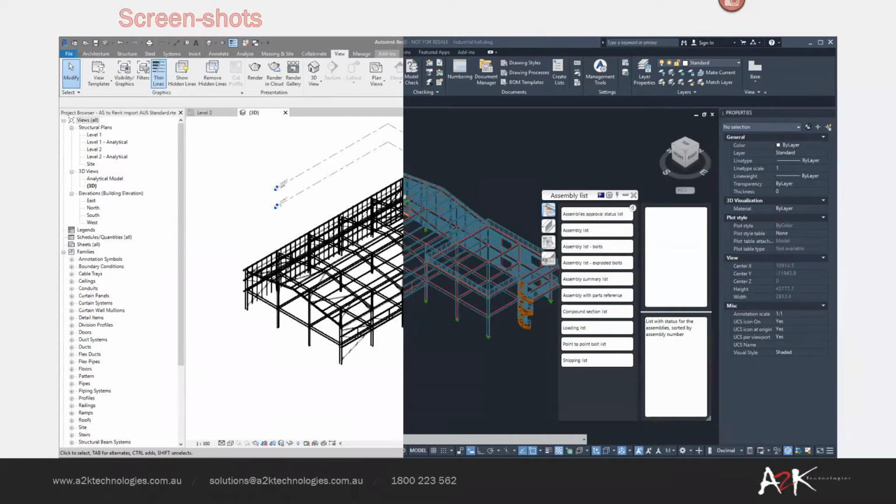The reason you would then push that through to Advanced Steel is that Advanced Steel has the ability to get out fabrications in 2 clicks. Obviously, there is a lot of customization and amendment that you can do, but you can potentially get fabrication drawings straight out.